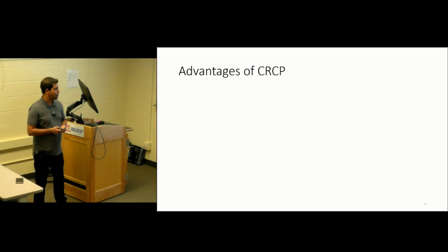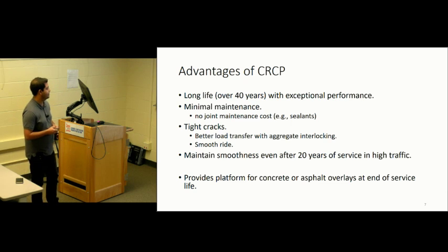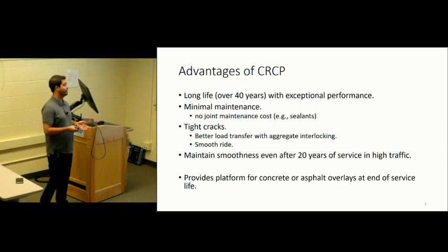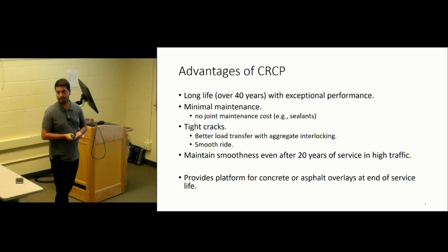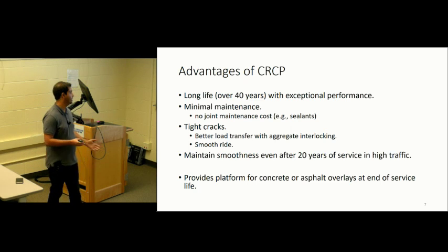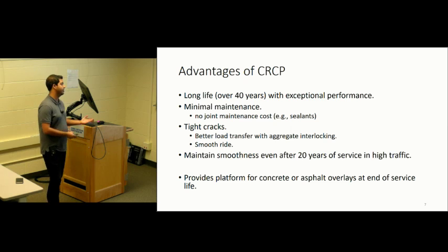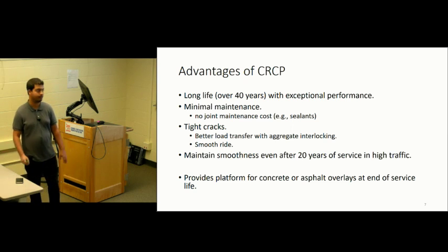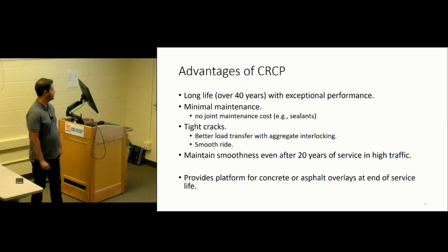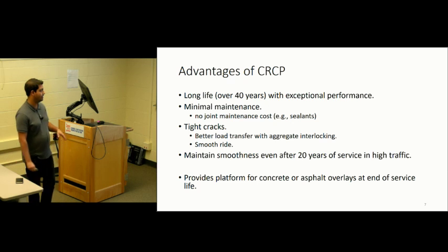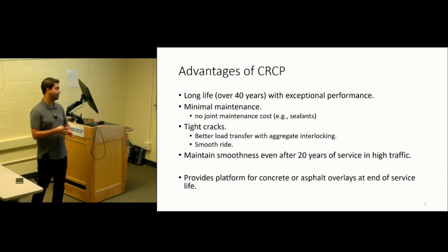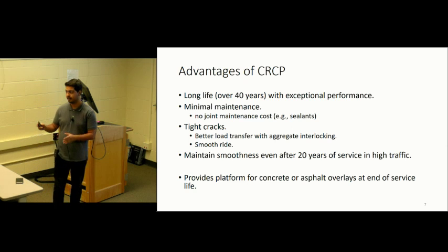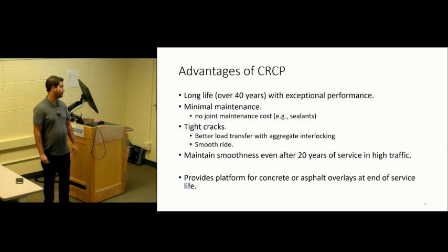So let's talk about some of the advantages of CRCP. The main advantage is it has a very long life, over 40 years of exceptional performance. And there is minimal maintenance because there are no man-made joints. So there is no use of sealant or other maintenance costs related to any joint. And the cracks are really tight, so it provides better load transfer because of aggregate interlocking. And as the cracks are very small, it provides a smoother ride.